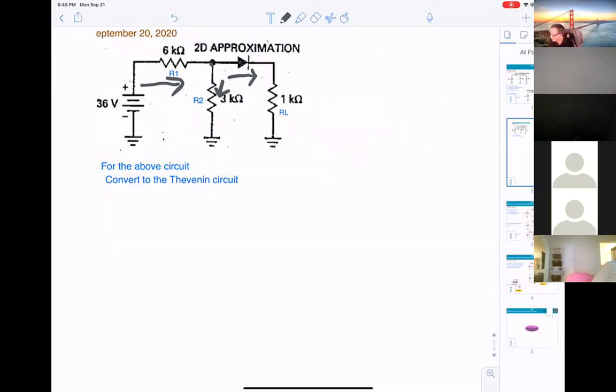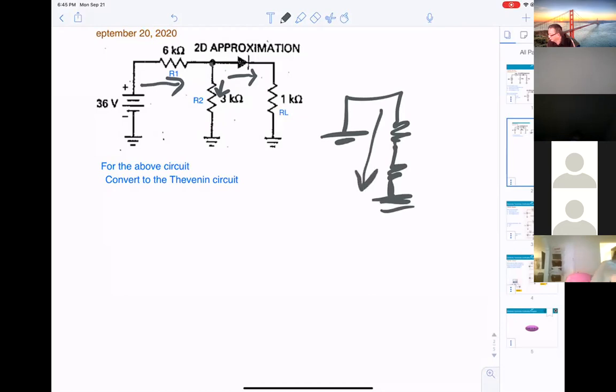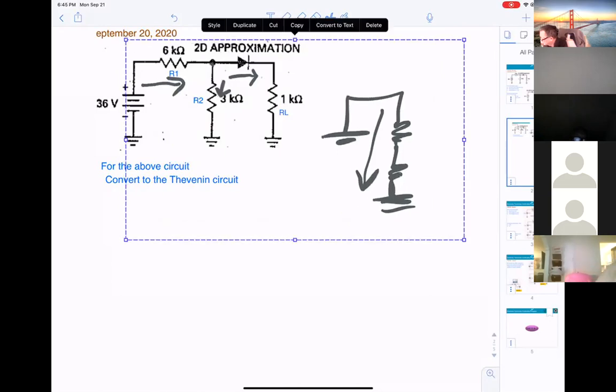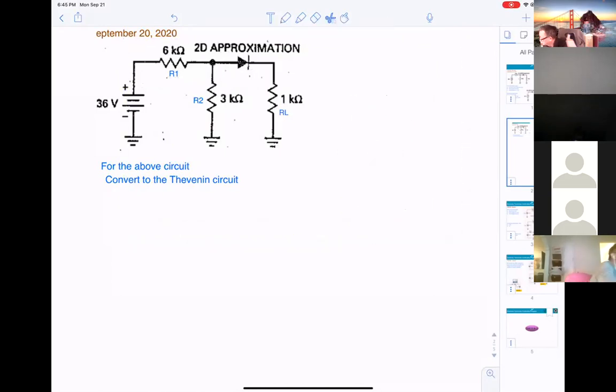If you get only one source here, and you get a resistor here to ground, now voltage divider works, because the current will be the same current. But with a different current, it cannot be voltage divider. So on our original problem, where you got the parallel circuit, that you do the superposition to make that work.